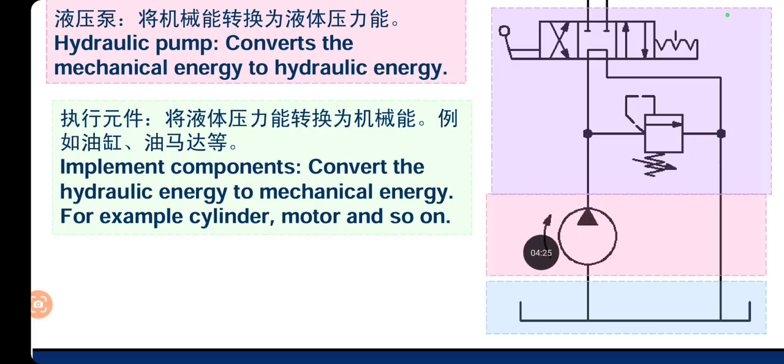In this case, there is no line on the pump, which indicates that it is a fixed displacement pump. You can also say it's a gear type pump. The reservoir is on the top, at height, so the oil which comes to the pump comes by gravity.